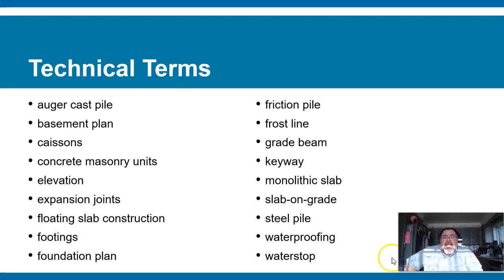And there will be a keyway so that the concrete is not poured flat against flat and that moves. There's a channel so that when you pour, the concrete can't move because it's like Legos. It snaps into a little groove. Think of Legos, except a long skinny channel instead of round holes.